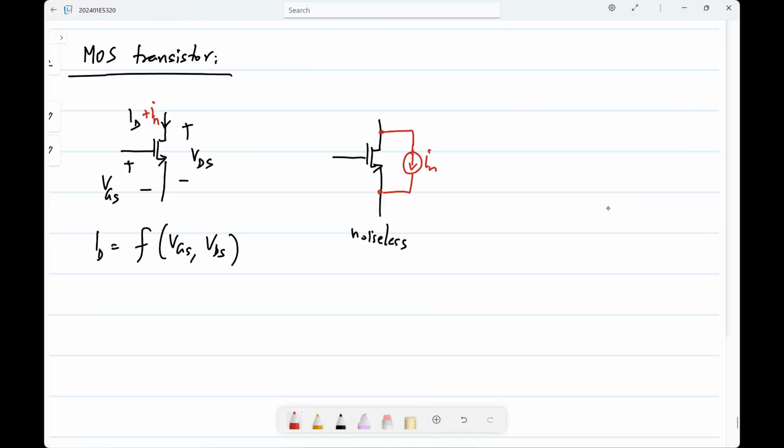In a MOS transistor, you produce them by forming the inversion layer by applying some bias. That's all that is there. Otherwise, it's the same. What is the current carrying mechanism in a resistor and in a MOS transistor? Drift, right? It is drift. So, in that case, you will have thermal noise.